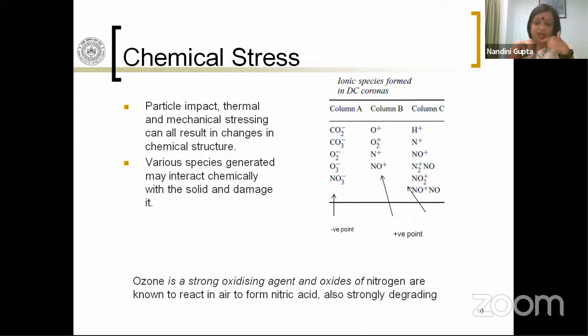So partial discharges in themselves, you often don't care. And you may rest assured that if you have an insulation in service, partial discharges are definitely happening within the insulation. It is not always a cause for immediate worry, but over a long period of time, as the material ages, partial discharges can reduce the lifetime of your insulation in power apparatus.